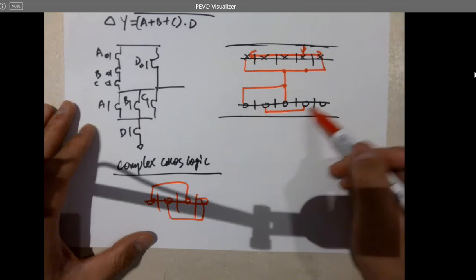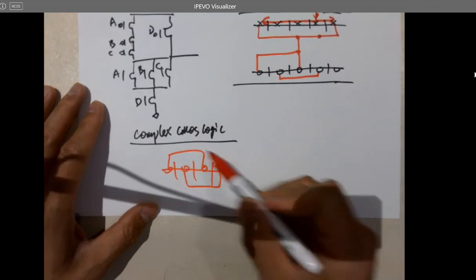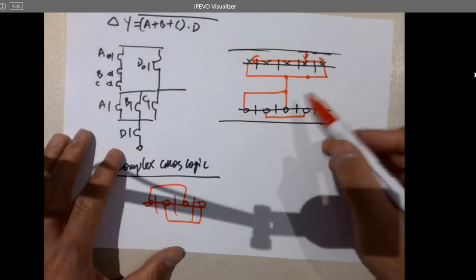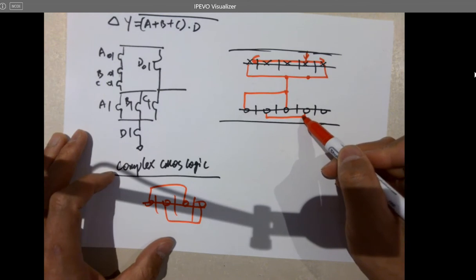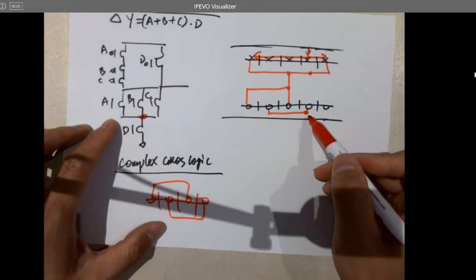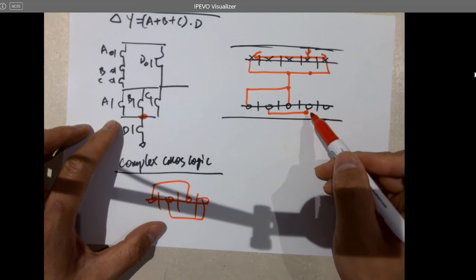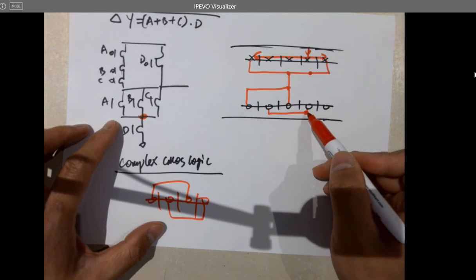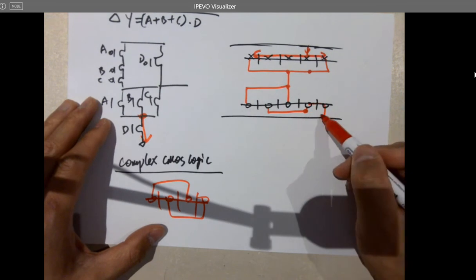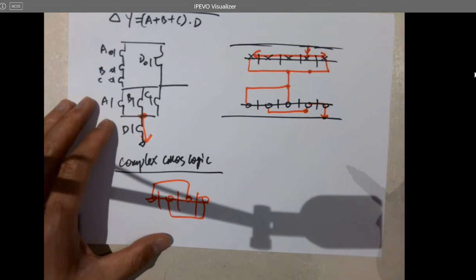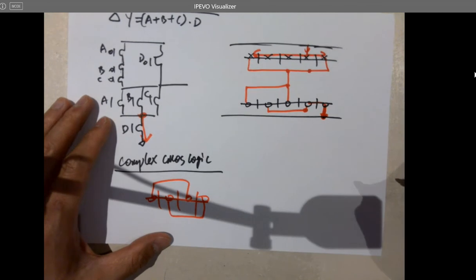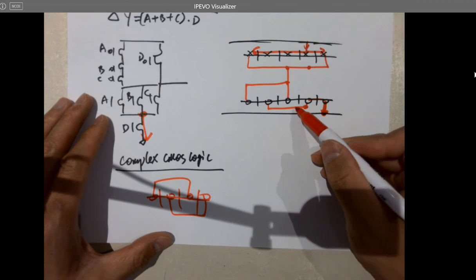So this part, remember, that's 3 transistors in parallel, right? The structure. Just keep using that. So we're getting that here. And here's the output. That's the output. So this node is this node. Now, is that true? You agree with that? Okay. And after that, just boom, ground. After that, ground. Done. So we need a final connection here to the ground. Do we need to short this to ground as well?